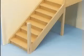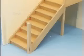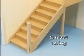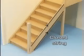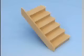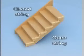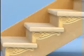A wall string has its outer surface fixed to a wall. A closed string, sometimes called a housed string, has parallel top and bottom edges. An open string, sometimes called a cut string, has its top edge cut to follow the contours of the treads and risers. In an open string stair, the wall string is usually a closed string. Decorative brackets are often added as a design feature.